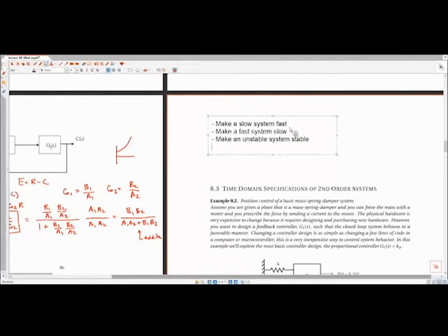As you get into the end of project part 2, you're going to see that in the case of your pendulum system, at any angle greater than pi over 2, one of your poles is going to pop into the right half plane, and that's going to be an unstable system, right? And so we are able, with control, to still control that pendulum angle, even though it's in the right half plane, because we can move, via control systems, those poles into the left half plane.